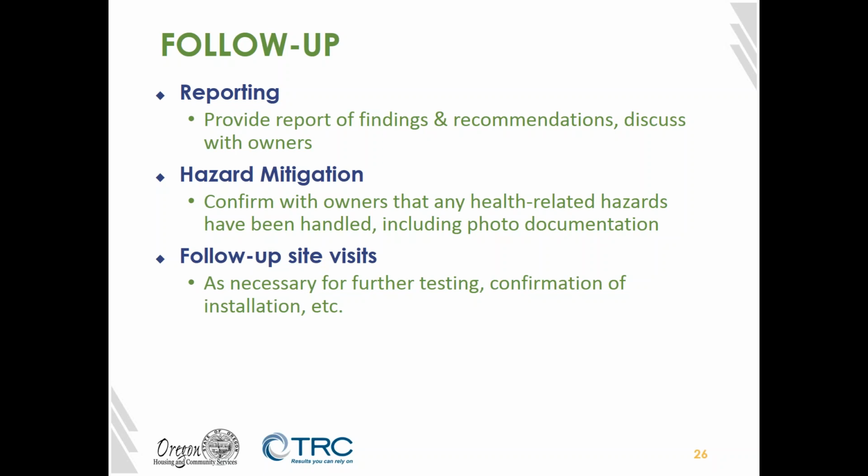And this may actually move into follow-up site visits where we come out and we determine that it has been taken care of. Or these site visits may be something more energy related, where if we decide that we want to do further testing on, for example, duct leakage and determine exactly how much leakage there is, and we need to come out a second time to test the ducts or do duct blasting testing or something along those lines.